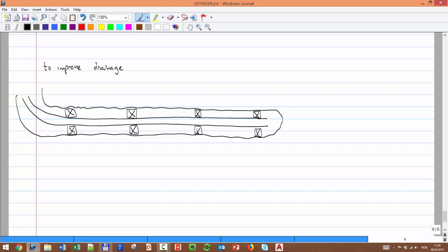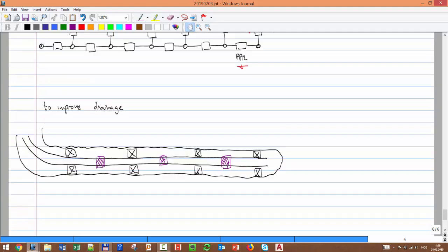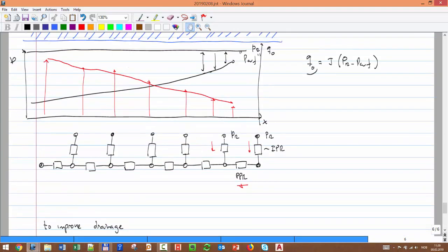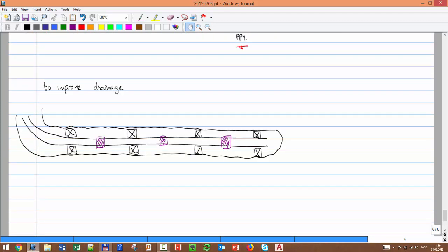And then for each one of these regions, I can put exactly the same thing, the sliding sleeve, the ICV, AICV that we discussed before, right? To try to control. If I have too much pressure drop, too high delta P, I can simply add some artificial delta P to try to equalize production.